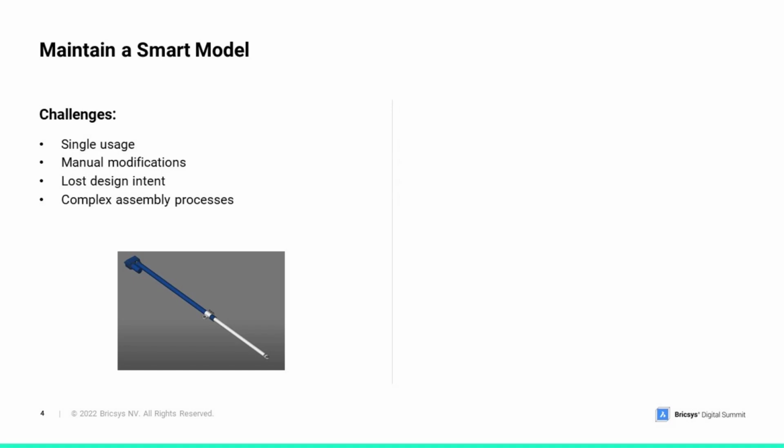In contrast, non-parametric designs lack the agility to changes. If a part is to be changed, the rest of the model will not adapt correctly. An unconstrained assembly would behave as a group of parts combined together without sufficient definition of how they should mechanically interact with one another. That will also not allow checking product kinematics to tackle related issues. Let's go back to our demo and see how we can easily work with parameters and constraints within the assembly context in BricsCAD.